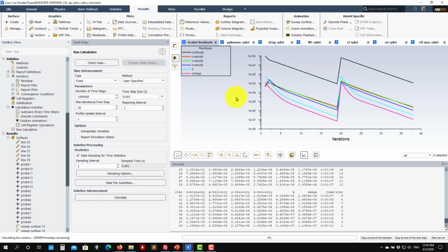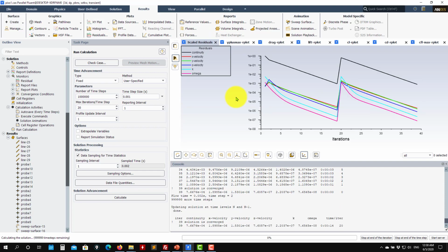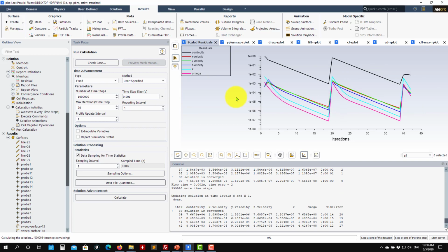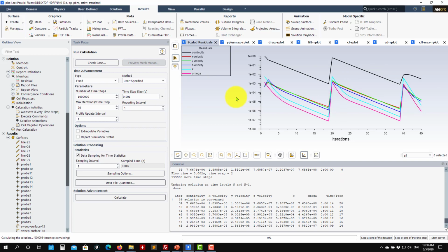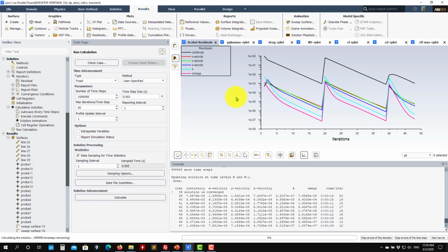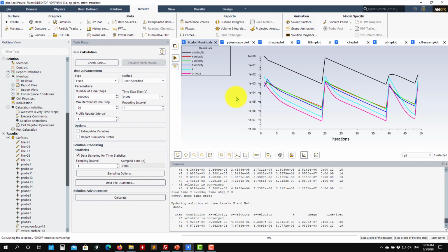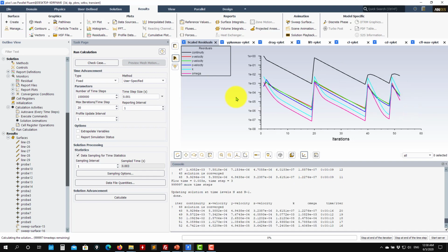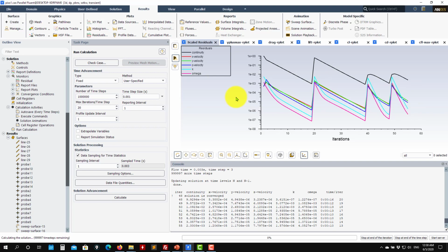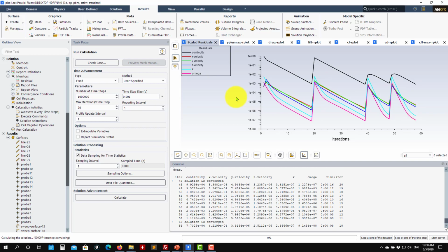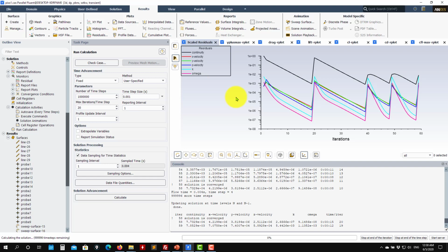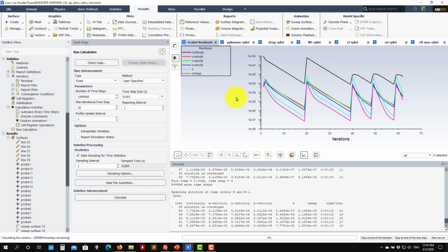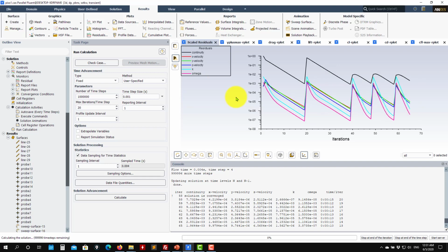Okay, so as we look here, we're going to see the proper behavior. And this point is just waiting. So you need to monitor quantities, CD, CL, see when the solution is statistically steady from a turbulent point of view. And then you can say, okay, I will stop here. So let's run this solution, and let's see what we have.